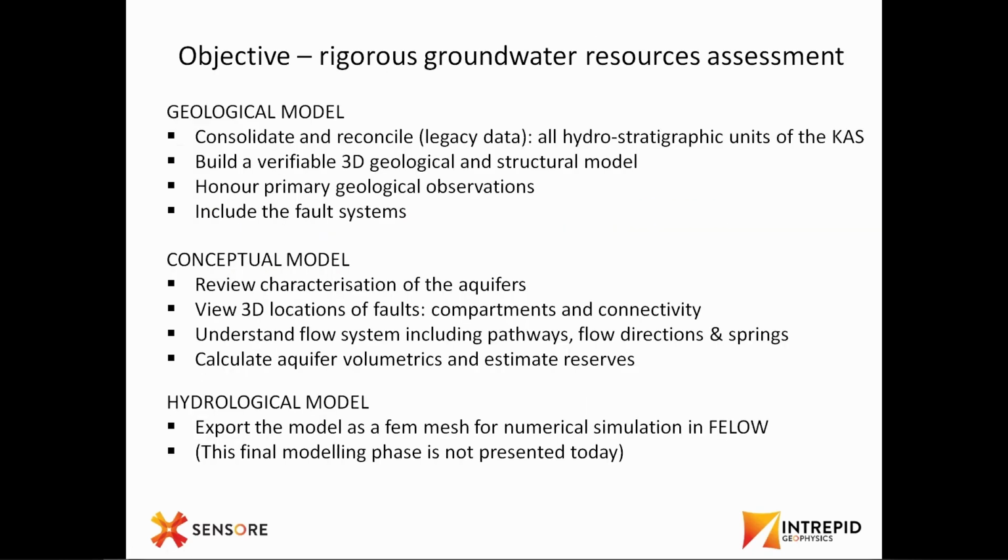So we have different objectives. First, we create a geological model, by understanding your data, what data you have available, and what the hydrostratigraphic units of your study area are. We verify those data and build a geological, structural model that honors all your primary observations, and also include a fault system in it.